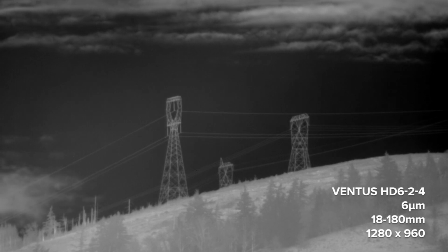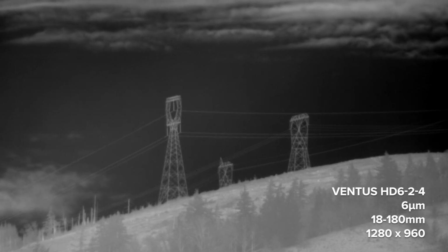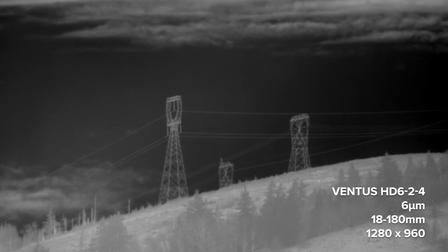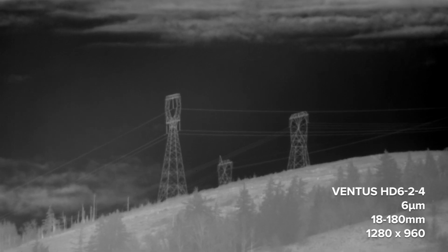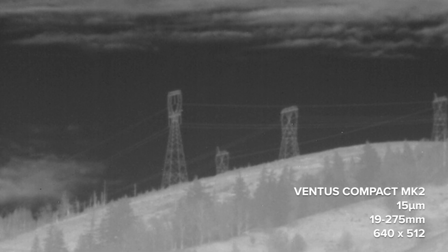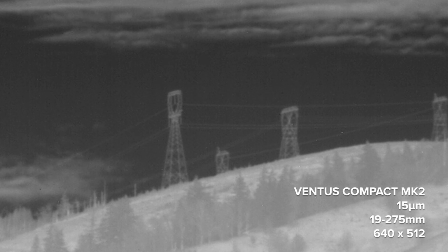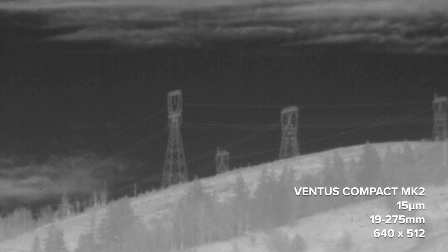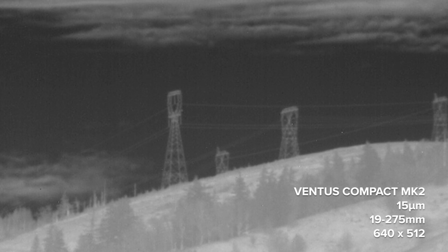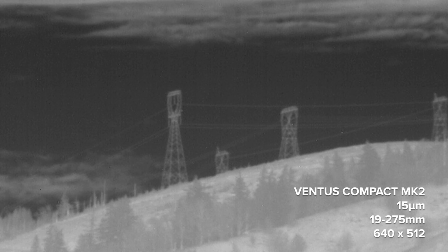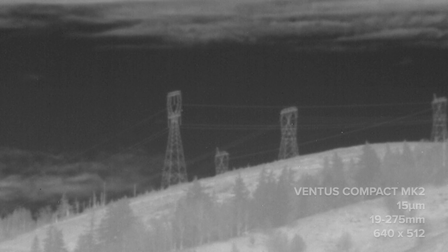And the higher MTF image clearly gives you a better viewing of the 1-inch wide aluminum transmission lines that you can see strung from tower to tower. Whereas on the lower MTF system, you can see elements of blurring on these high spatial frequency features in that scene. The 1-inch aluminum lines are not as clear, and you can't see quite the detail on the towers.